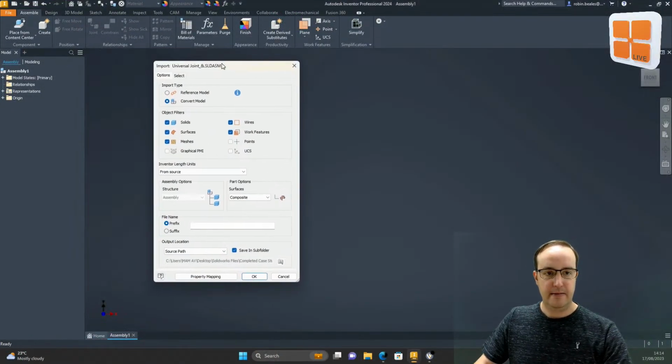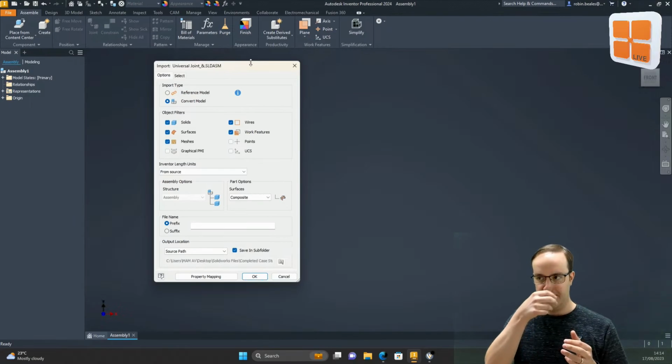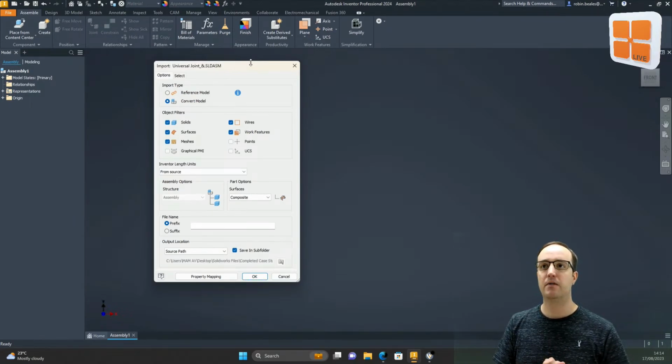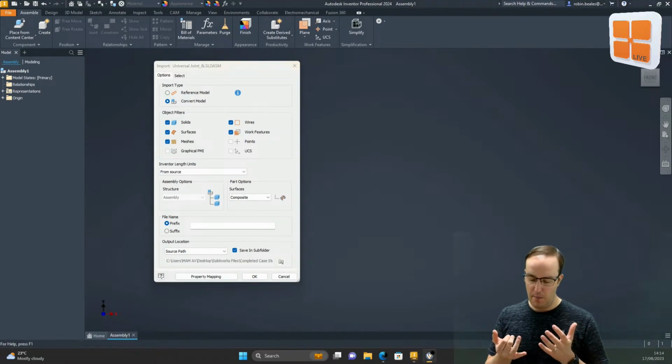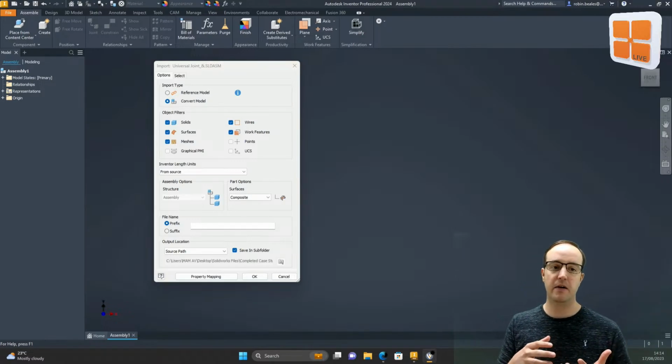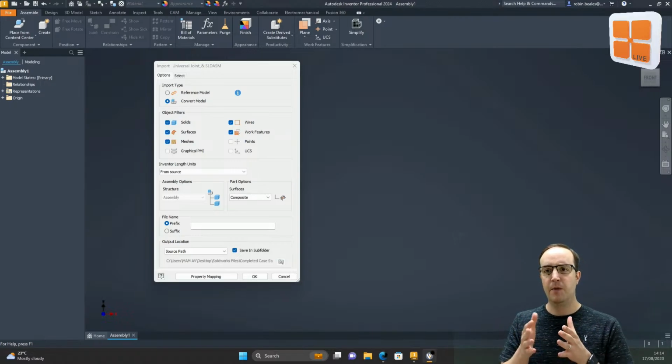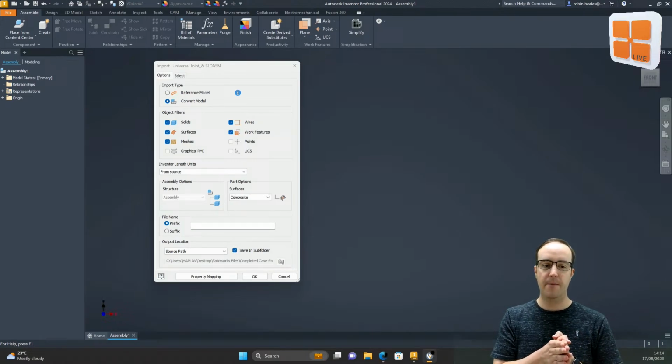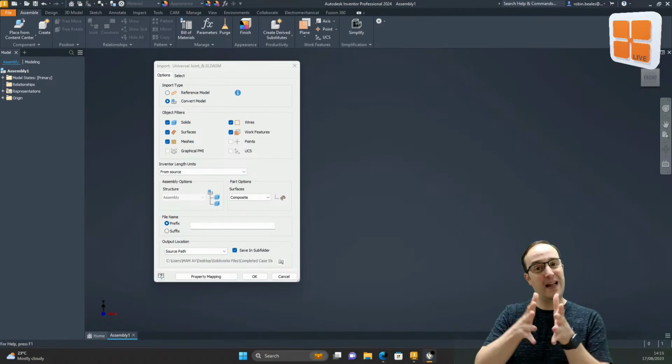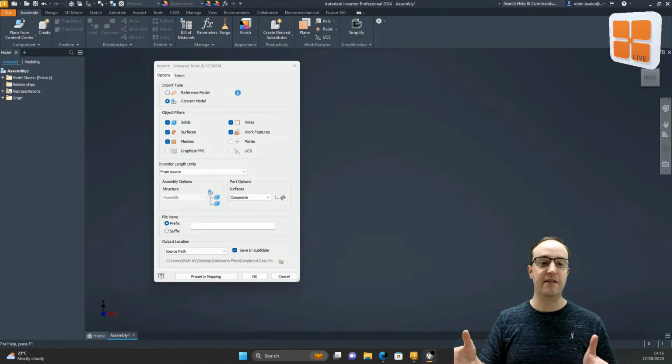Good, we're back. So we've imported this SolidWorks assembly, this SLDASM file. And what that assembly is going to do is give us two options. When we're working with external data inside of Inventor, we can use that file as a reference. Think of it a bit like an XREF from a CAD perspective. It will link to that file and keep a live reference to that particular component, which is actually quite useful. So aside from potentially transitioning over to an Autodesk ecosystem, if you're collaborating with someone outside of the Autodesk interface, we've got the ability to create a live reference to their files.